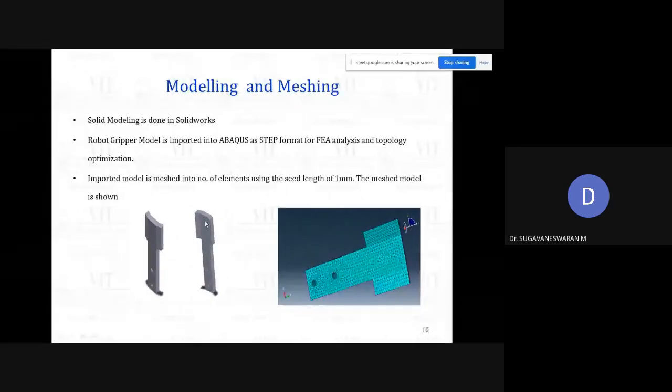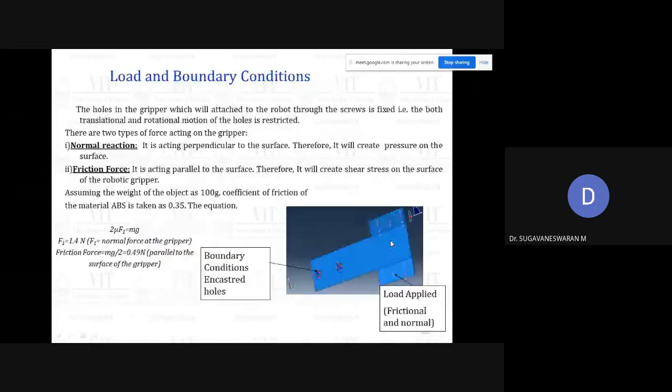So this is the internal shape, and this shape should be as per the profile of a component. For that reason, they went for additive manufacturing, because as per the shape, they want to immediately create a plastic component. So they started with the CAD model, and they converted the CAD model into a mesh model, an FEA mesh model.